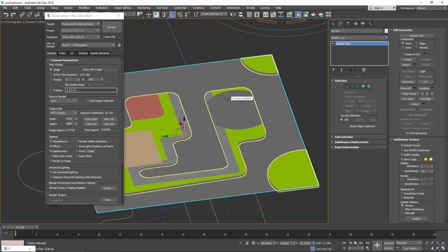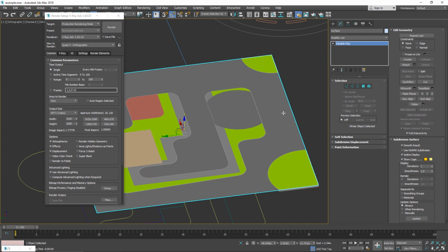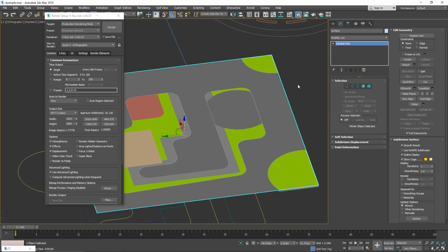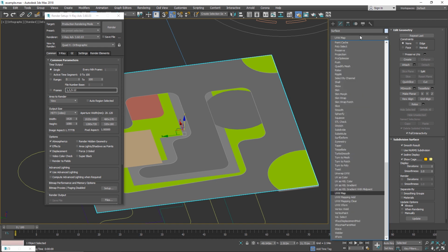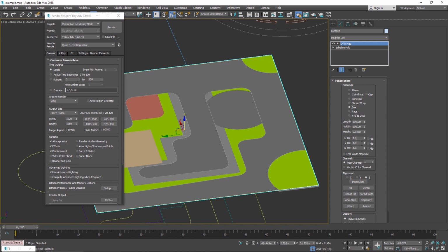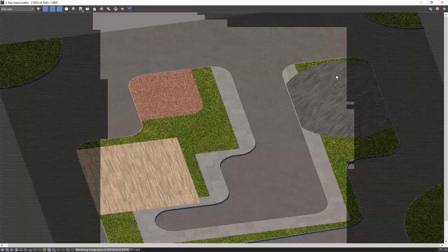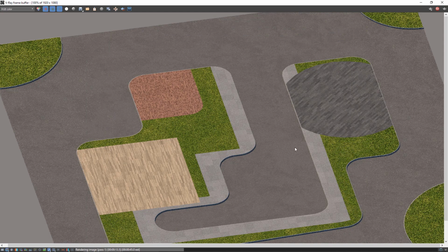All materials in Cityscape are required to have real-world mapping. When you generate an element, Cityscape automatically applies real-world mapping to it. But if it's a surface object, and we don't use the Modify Surface tab or the road texture tool, which automates the mapping process, then we need to apply a UVW map, texture, and check the real-world map size. Okay, so now next time we render, it's a different story. Again, you can see that this part is rotated.